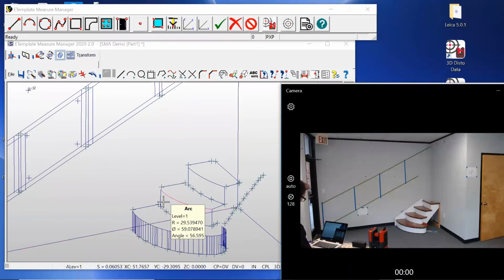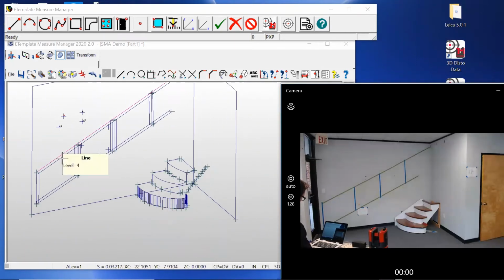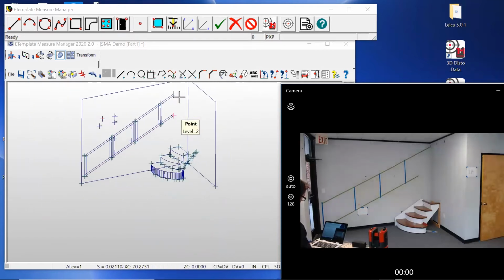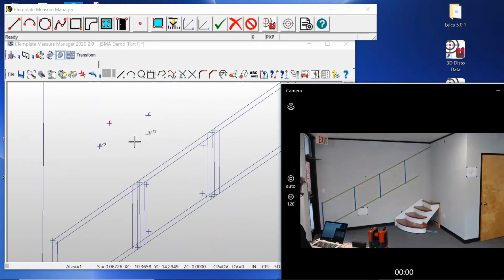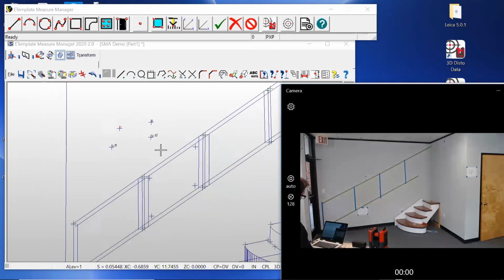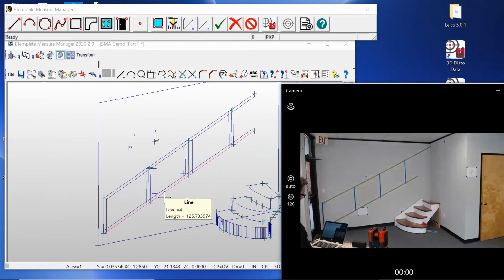So if I want to capture the radiuses, I can capture those through point taking and also the stringer, along with the railing system up the wall in a 3-dimensional space, and also be able to take points on a plane. So if I want to know if the wall is plumb, or if it has high points or low points, if it's leaning back at the top or at the bottom, I can determine that by shooting points and then using our wall analysis feature. Then the 0 indicates the high point of the wall, and it shows that I'm 1/8 below that point in 3/32 here. So if I have a series of those points at the top part of the wall and the bottom of the wall, I can see what that wall's doing.